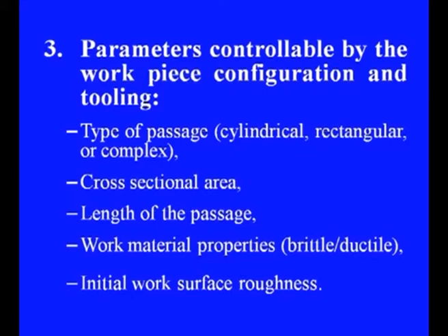Then initial work surface roughness also matters, because the workpiece we will be using in this process will be only for finishing. Therefore, the previous process, whether it is rough turning or finish turning, or whether it is milling or grinding or a reamed surface, might cause some effect on the final surface that will be achieved, or otherwise we may need to process the surface for a longer time depending on the initial surface roughness received.